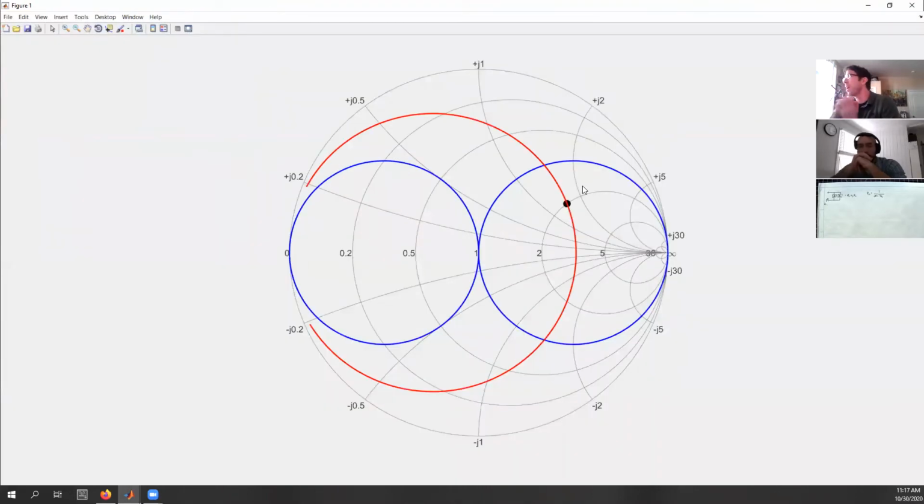I just hypothetically added some parallel susceptance, and I pretended it was a knob that I could dial to plus or minus values. So you notice by putting a susceptance in parallel, which hypothetically could just be a capacitor or an inductor, I follow along these same admittance circles here. So this was the admittance circle when the real part was matched, and these are just admittance circles now when they're sort of off matched.